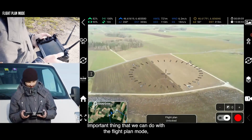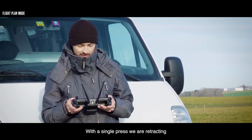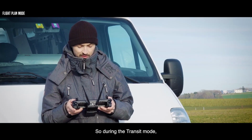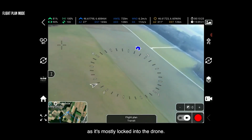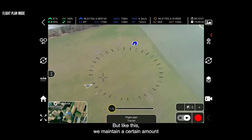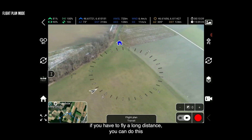Last important thing that we can do during the flight plan is to retract the payload. Again with a single press, we are retracting, and we are now in what we call the transit mode. During transit mode, the payload is up inside the drone body, so we get low stabilization as it's mostly locked into the drone, but we maintain a certain amount of visibility of what's happening below us, and we reduce drag, which will be extremely useful if you have to fly a long distance.